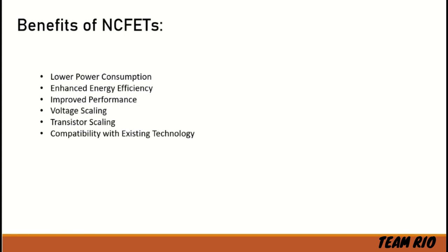Then voltage scaling. NCFETs enable voltage scaling, allowing electronic devices to operate at lower voltages without compromising performance. This is particularly beneficial for battery powered devices and energy efficient systems. Then transistor scaling. With NCFETs, it becomes possible to further scale down the size of transistors, paving the way for more advanced and densely packed integrated circuits.